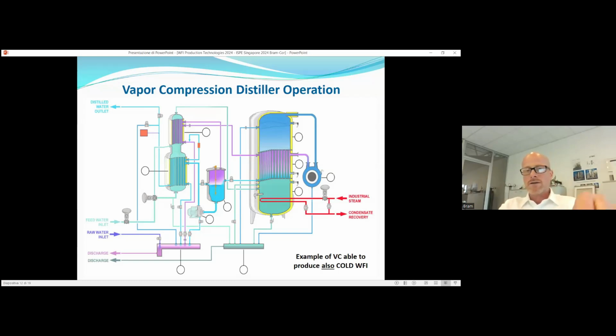The feed water starts boiling, goes into the tube, then evaporates into steam, which is still wet steam. In the wet particles, to make it simple, the contaminants remain. The first separation, as we indicated before, is by gravity.